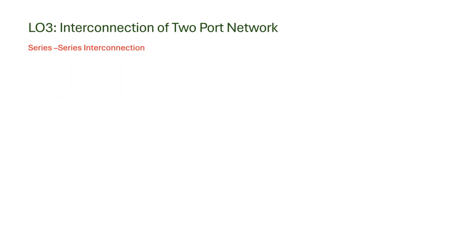So let us start with series connection. In the question paper, they ask: derive the two-port equation for series interconnection of two-port networks. So now let us take two-port networks. I will write here the way you have to write in the exam also.